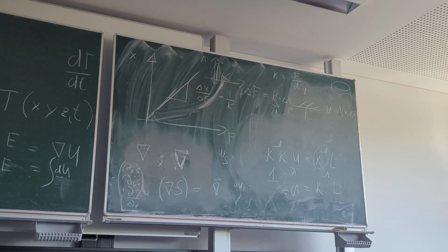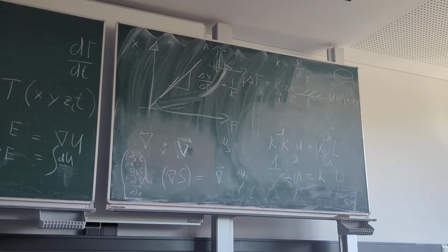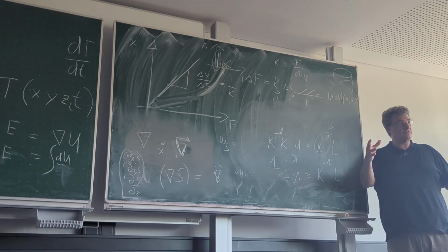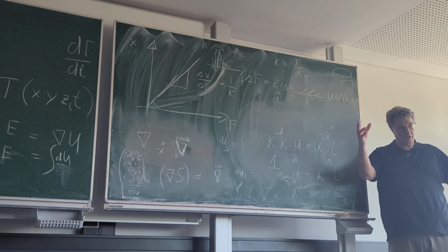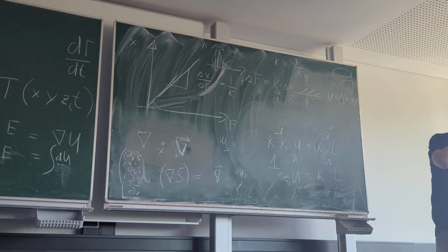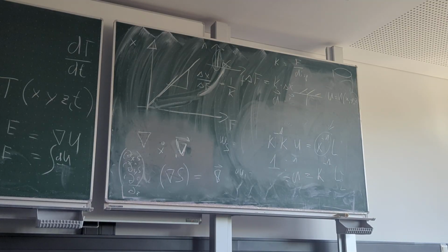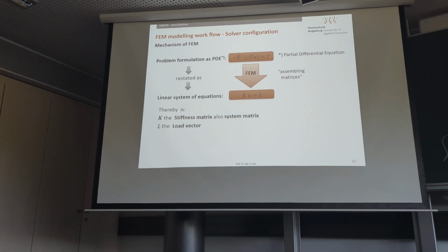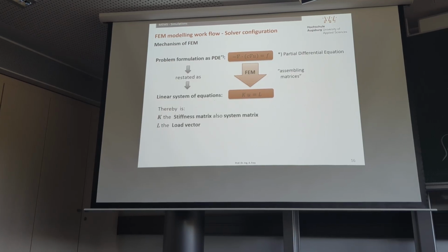Why are we not finished with this? Basically, because you're probably limited by the size of the matrix you can invert. You know, if it gets larger and larger, it will not fit in your memory, and even if it fits in there, it takes more and more time to do that operation. So at a certain moment, it's not reasonable. If you run out of memory with this direct solution method, or it just takes too long, then we need other methods, iterative methods.